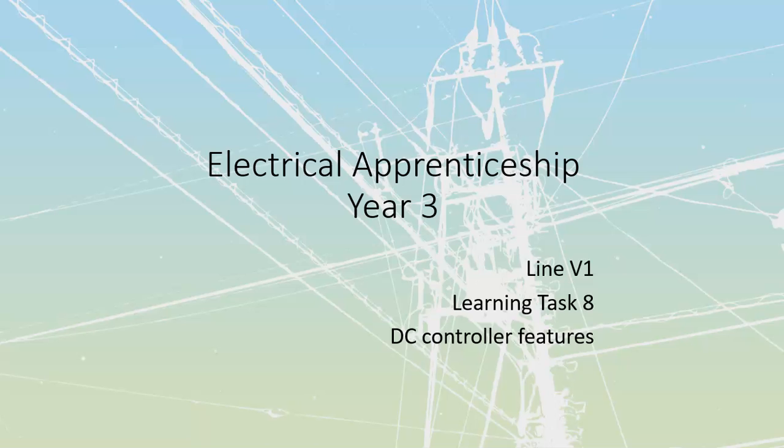If I control the amount of current, I'm going to be able to control the torque that I'm going to have out of it, and to provide the correct operating sequence and speed control of any sort of driven mechanical system. And these are the 3 main purposes of any motor starter, whether it's for AC or DC.